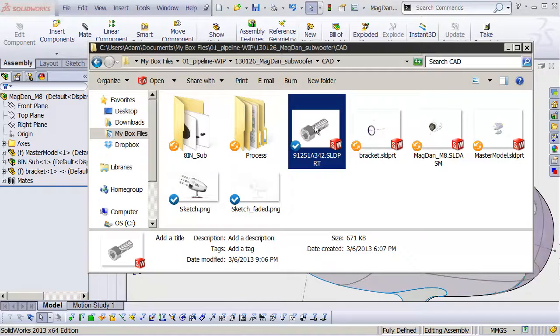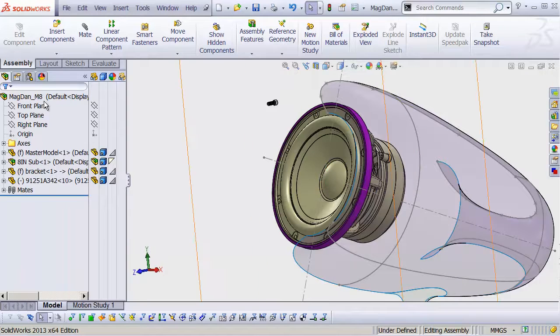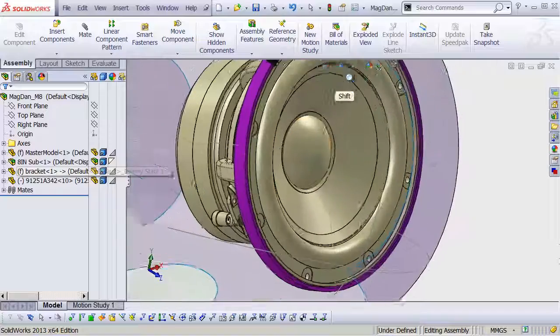Now this is cosmetic, of course, but we downloaded this bolt from McMaster-Carr. Now let's just drag that up into our assembly here and drop it. And once again, you should be editing the top level assembly when you do that. If you happen to be editing a part in context, it'll give you an error message. But I'm in the assembly, and I've dropped in my part.